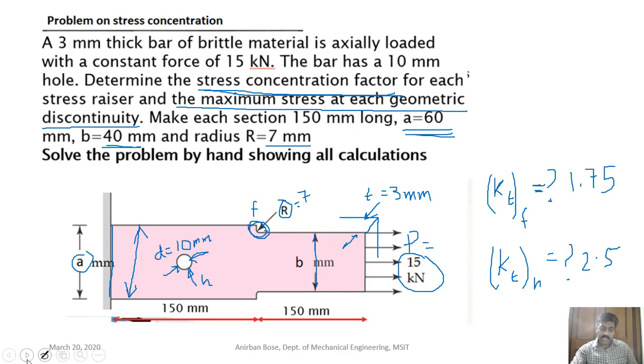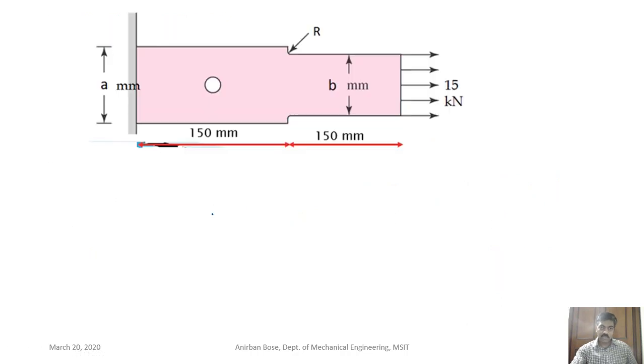First do it for the fillet. Let's write the formula for the maximum stress, and that is Kt into nominal stress. Now we are solving it for the fillet.